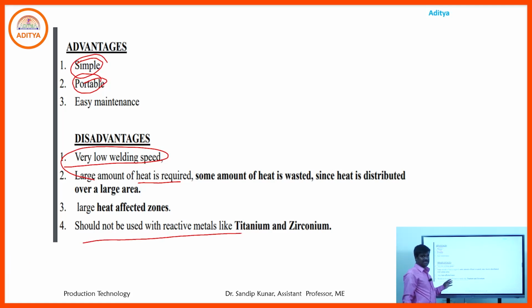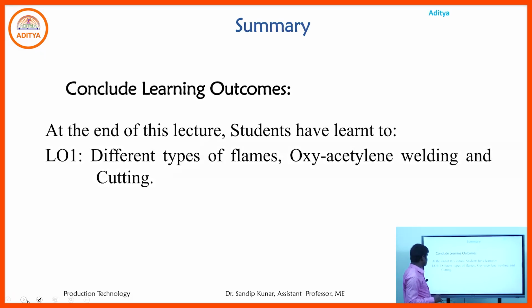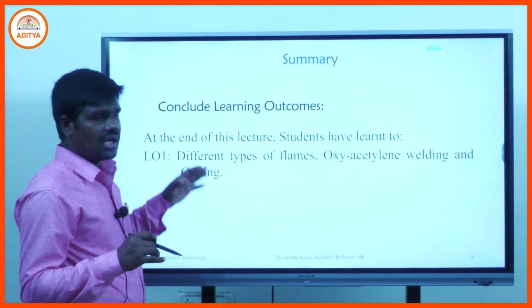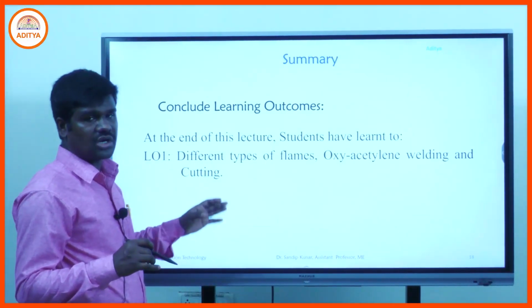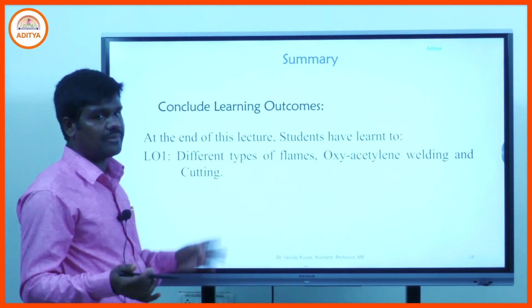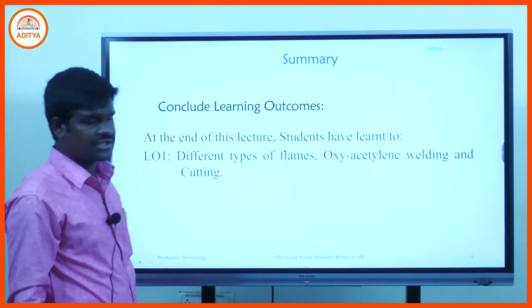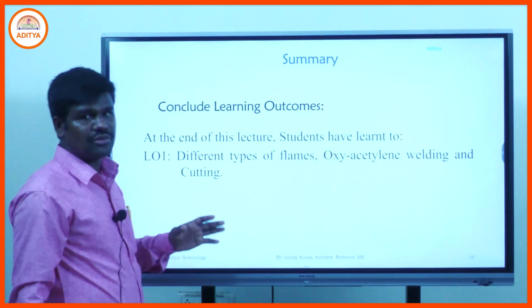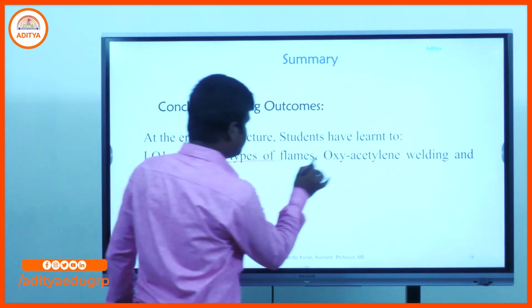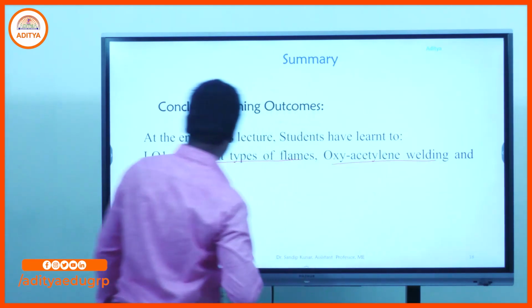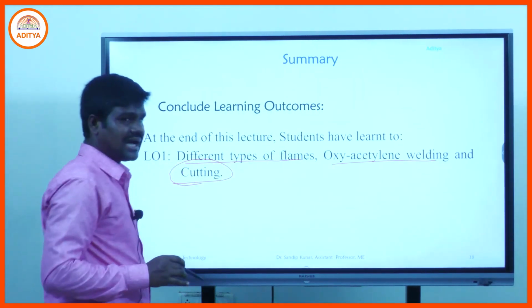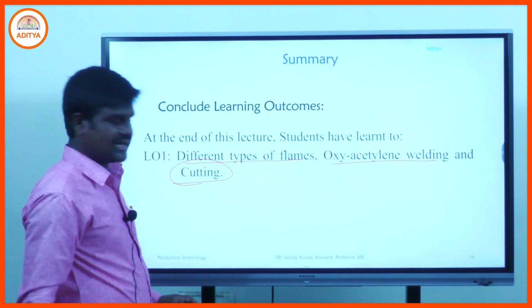In gas welding operations we also do not use special materials like titanium and zirconium, because these materials are reactive with oxygen. For these materials we use other welding methods. At the end of this lecture, students will be able to learn the different types of flames and oxyacetylene welding and cutting.